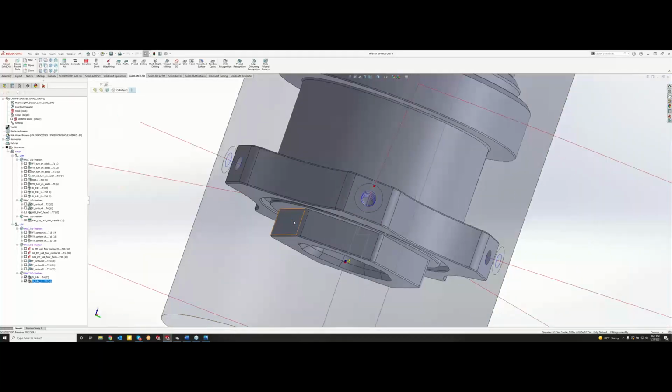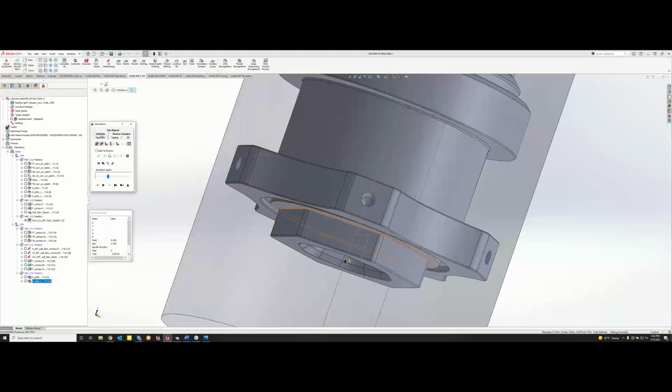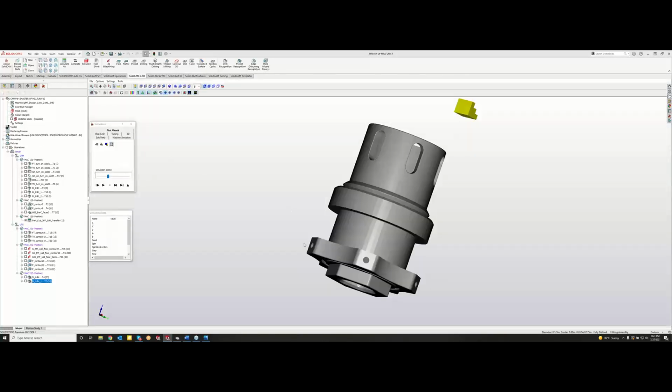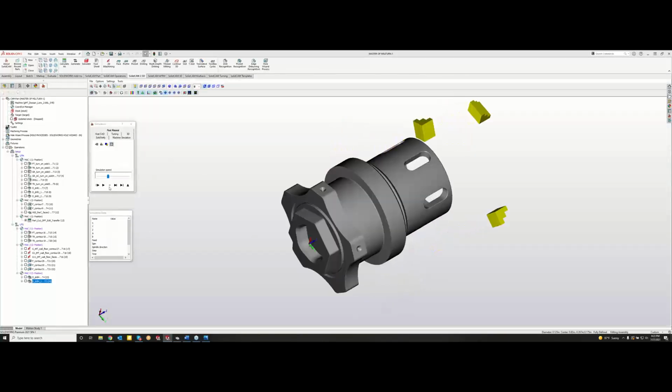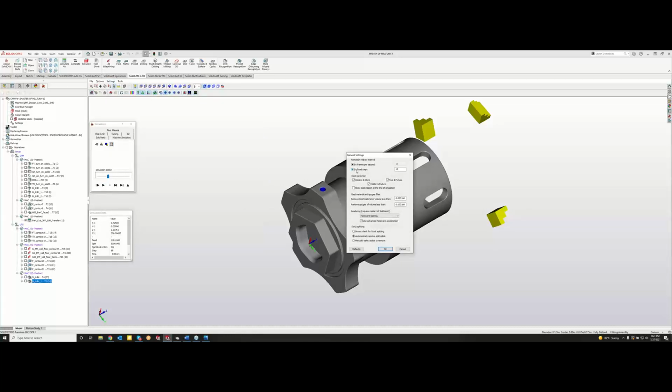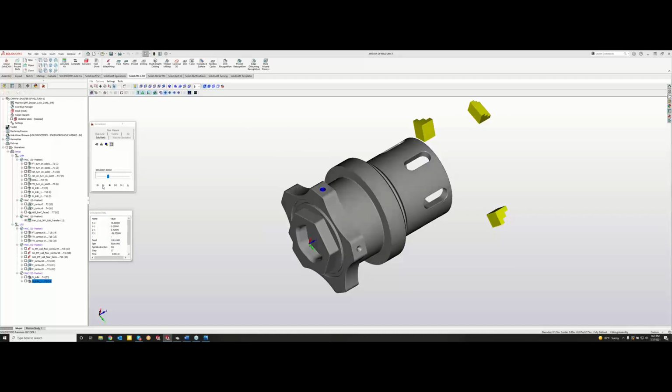And now if we simulate this, you can see that we're doing our drilling all the way around. Now, if I go to here, if I fix steps, do 1, we should be able to see it pecking. So you can kind of see it's pecking out.